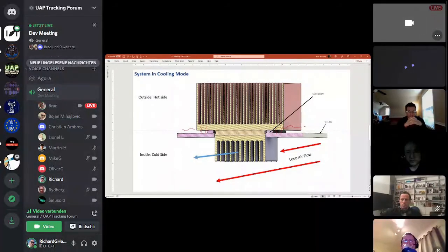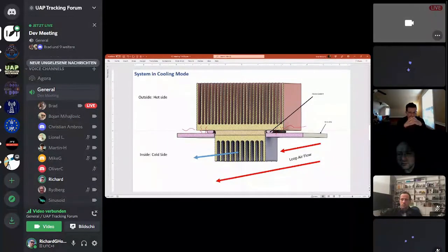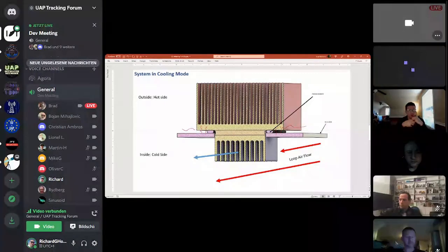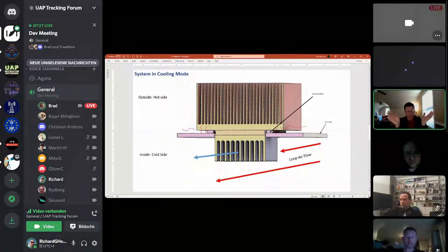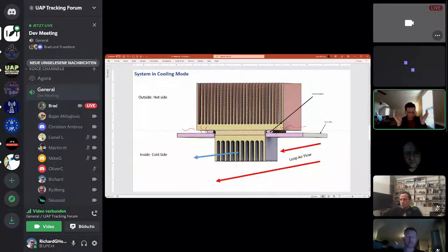What I did in my design is I used your copper standoffs, the 1mm on both sides of the peltier. So that would increase the thickness of the peltier to 5.75 millimeters. But it would be better if we could get the hot side completely off of the structure of the duct. Yeah, but we don't have only one hot side. It is a dual mode device. We're switching hot and cold. Yes, so exterior versus interior. The interior side needs to be smaller. I'm just trying to think of this only in terms of cooling mode because it's easy to make heat. The difficulty is going to be making cold. So I'm only going to be thinking about things in cooling mode when I'm talking now.